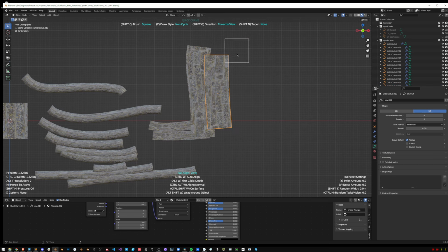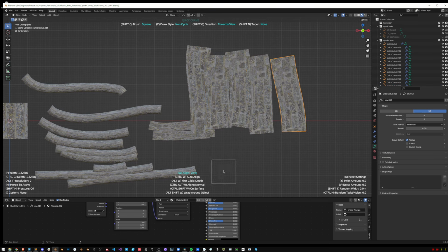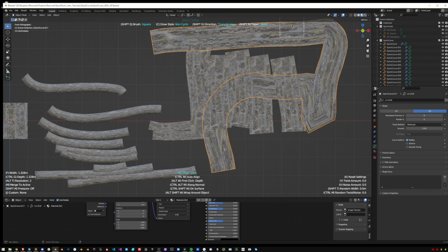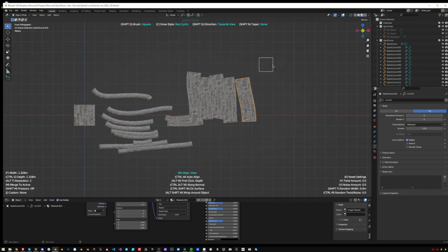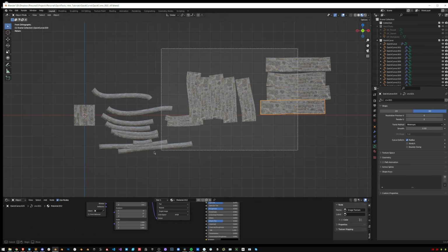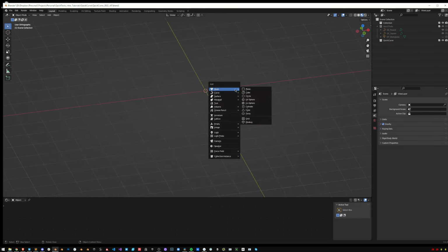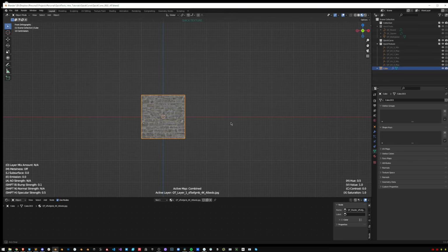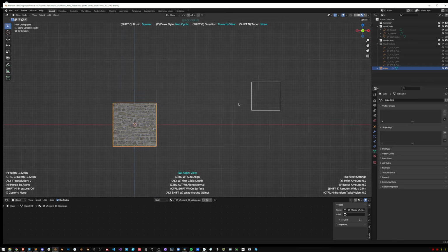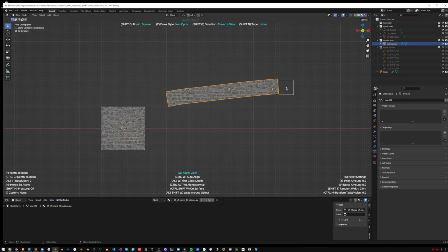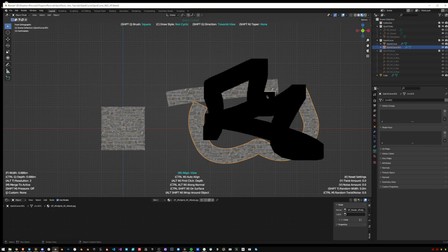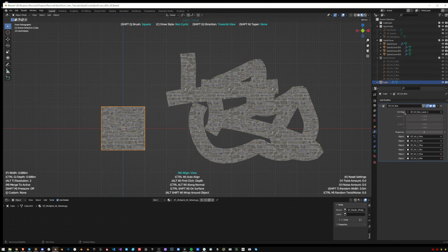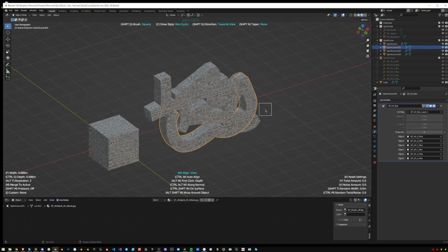But you'll see, here's the issue. It's all linked to the orientation of the curve. So if you start doing this, it gets weird. It works well when you're doing this. Now, if you make this material with QuickTexture, so for example, Control T, bring in the same material, and then you Control F, you've got material from active. It will be fixed because this is using the special QuickTexture procedural setup at the modifier level. So now it's not using the object's UVs.